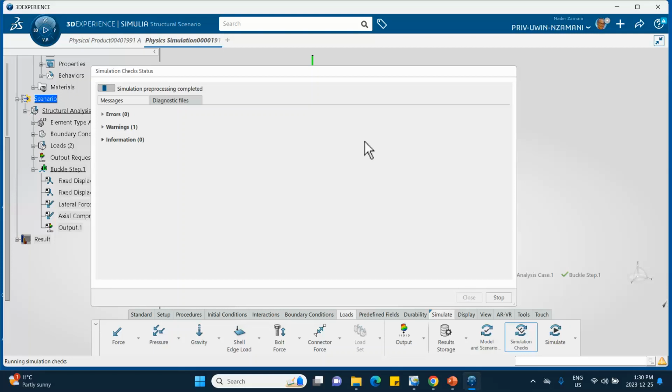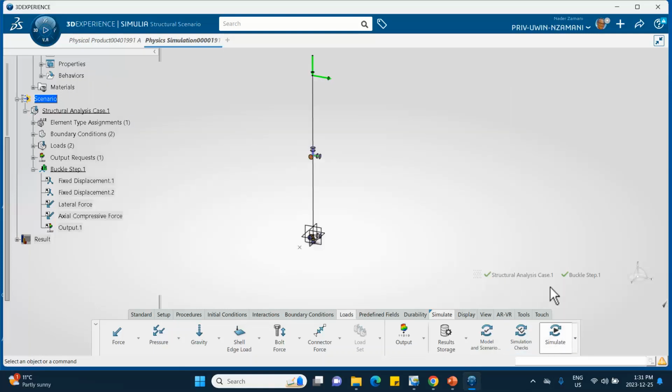I don't anticipate any issues here. And we are extracting 10 eigenvalues. If we get an error message about the number of iterations, we go and change that default value of 30 iterations to 100 or something along that line. This is fine. And now we're going to run it.